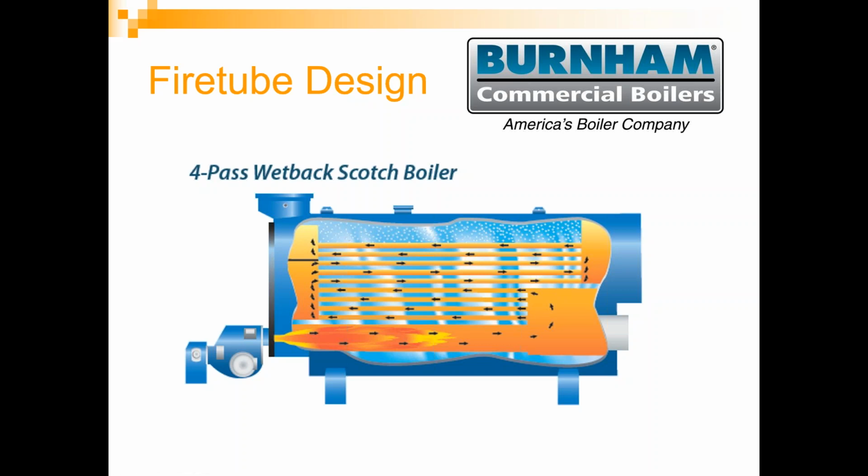Now there are downsides to Firetube boilers as well. If you have a 500 horsepower Firetube boiler, you could have 20 feet long tubes in it. One of the downsides of that is if you have it in a hot water system, you have varying return water temperatures, and with a 20 feet long straight tube, you can end up with what's called thermal shock because those tubes are going to expand and contract.